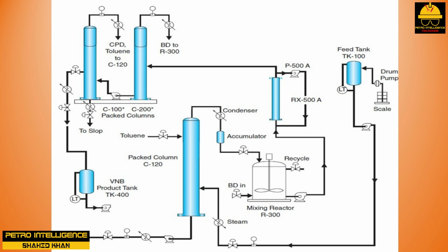A large centrifugal pump circulates the feed through the reactor as the synthesis reaction occurs. The reactor is mounted vertically, and flow moves clockwise through the tubes. Special inhibitors are added to the feed to limit the formation of insoluble polymer during operation. After the reaction occurs, a small percentage of VNB is formed.